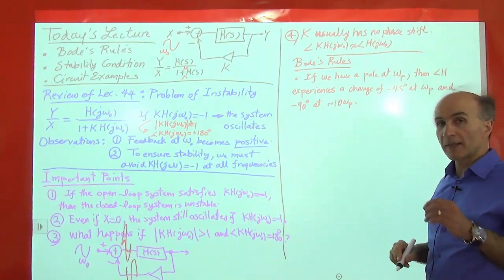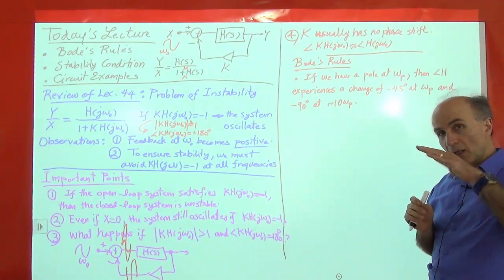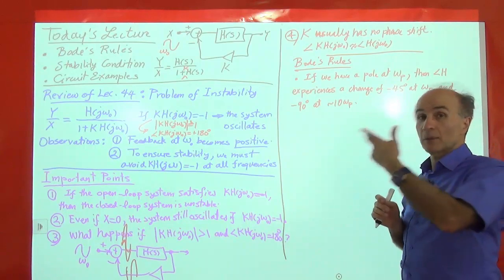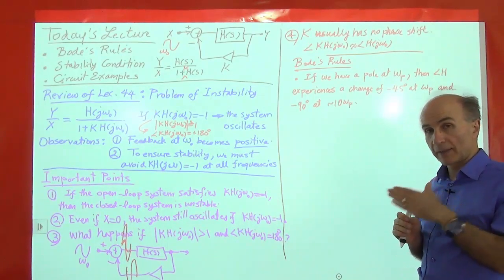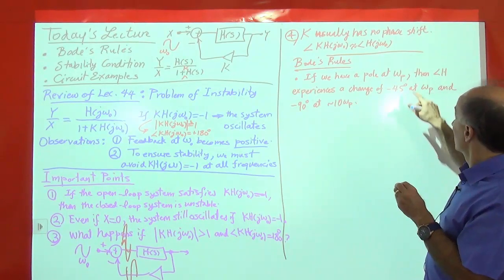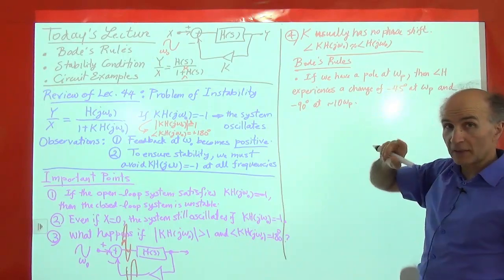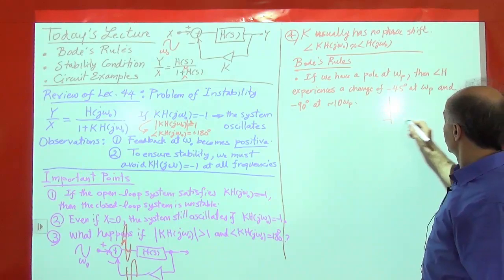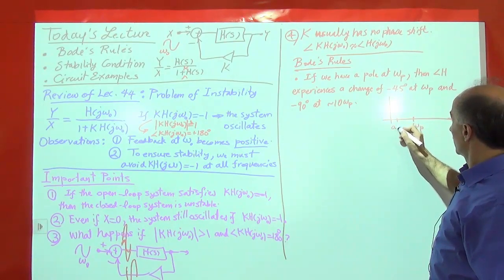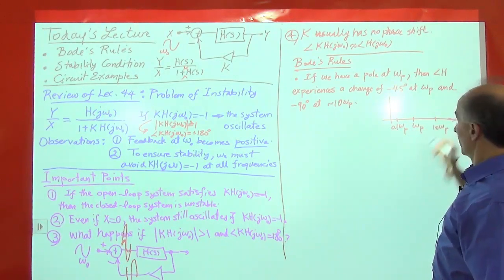All right, so all this means is that if I'm plotting the phase of a transfer function, when I reach the pole frequency, I have to go down by 45 degrees. And when I reach 10 times the pole frequency, I have to go down to minus 90 degrees. And we begin to feel the effect of this omega p at about 1/10 of omega p. So for a single pole system, it looks like this. Let's say you have a single pole. So we identify 0.1 omega p and 10 omega p on the omega axis.